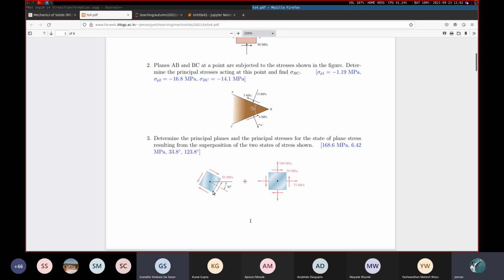Sir, and one more thing, can the Mohr circle be on the two sides of y-axis? Of course. If there is excessive stress at some point. Yeah, why not? So suppose your sigma P1 is positive and sigma P2 is negative, then only you will see, na? Yes, sir. It can be so that sigma P1 is equal to 10 megapascals, sigma P2 equal to minus 5 megapascal. So it will be asymmetrically oriented about the y-axis or the tau axis.